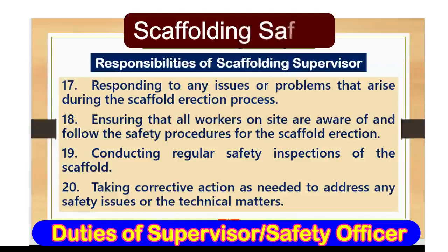Number 19, conducting regular safety inspections of the scaffold. And number 20, taking corrective action as needed to address any safety issues or technical matters. You can make a checklist, and once you are on site as the foreman or supervisor, you can ensure these 20 points.